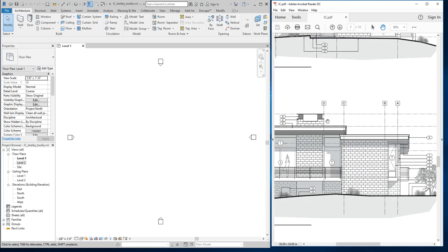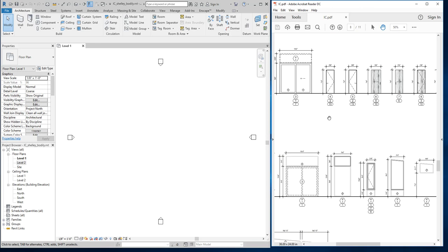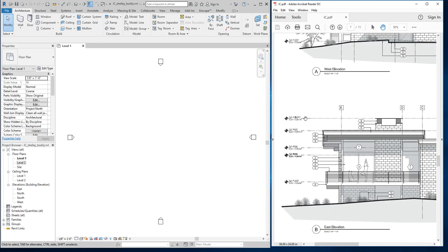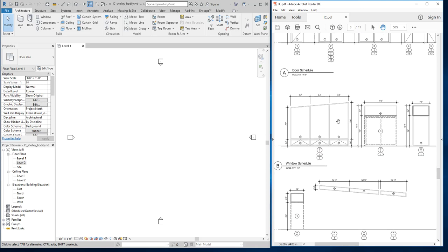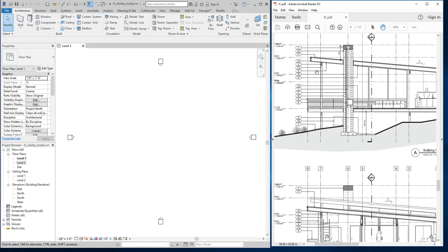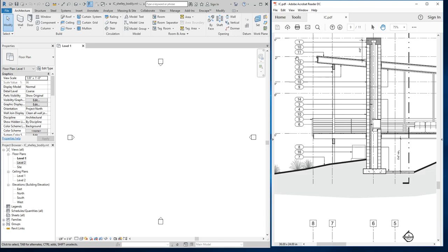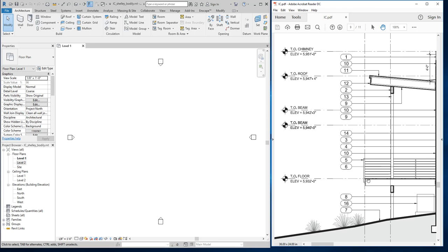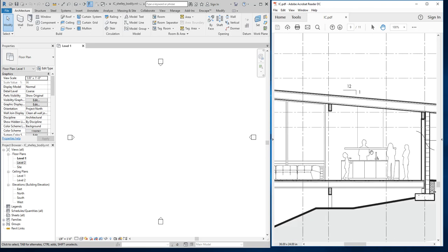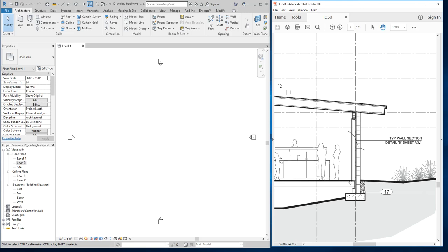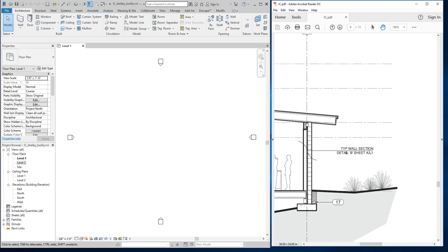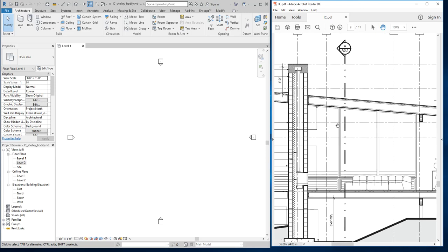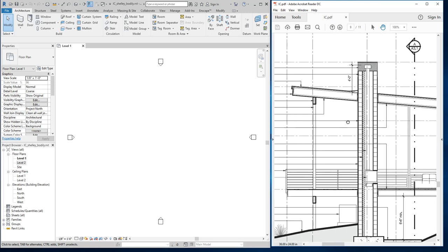This is another thing beginning designers are going to have to get used to: actually looking at the plans, right? And sort of figuring out all of the different datums, the heights for elements in your drawings, okay? A building elevation can give you those, but I think for our purposes we need to find a building section. And I'm just showing you how to find this out, but I've given you definitions in the assignment for this. So if you look here, the top of the main floor is 5932 feet above sea level. And if you look over here a little bit, that's the top of the floor we were just looking at. We have kind of this top of wall constraint here, okay? The roof does slope up, but we'll deal with that a little bit later.